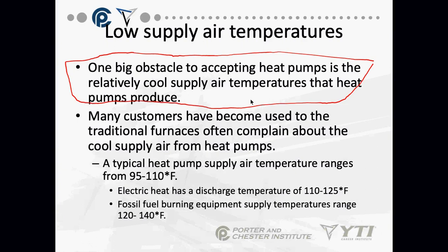Electric heat has a discharge of 110 to 125 degrees. In fossil fuel burning equipment, the supply temperatures reach 120 to 140. So heat pumps have a much lower supply air temperature than normal.